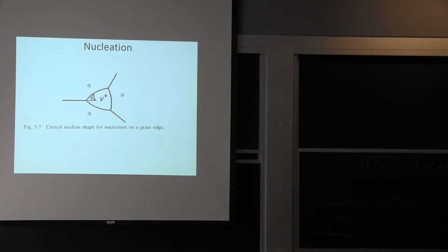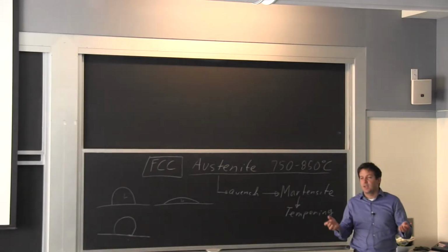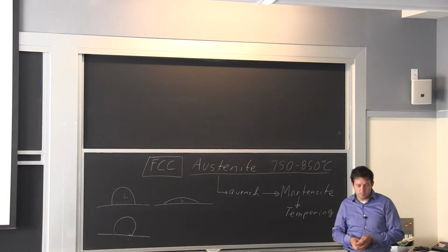So it takes time, and it takes diffusion, because you start with the composition being the same, and then all of a sudden, say you want 20% more of the nickel, if we go back to our example. So you need that 20% all of a sudden to be there just through thermal activation. So nickel is moving around in the microstructure. Things keep moving, moving, moving. At one point in time, you happen to have all that material in one spot, and it will grow instead of disappearing back. So think of it as having noise in a system, and instead of losing the noise, when it's stable, it will grow on you.